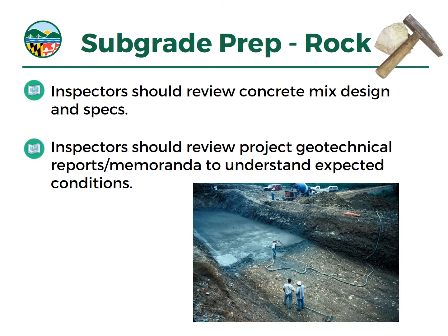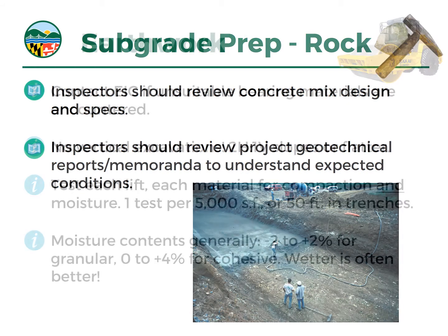The photo in this picture is an example of a foundation for a dam in Frederick County, and they actually use shotcrete to prepare the subgrade and make a working mat. That's a rock foundation, but clearly in the photo it looks like there's a lot of soil there, so I wasn't involved in it. I can't speak to the other preparation methods, but the dam has performed satisfactorily throughout its lifespan thus far.